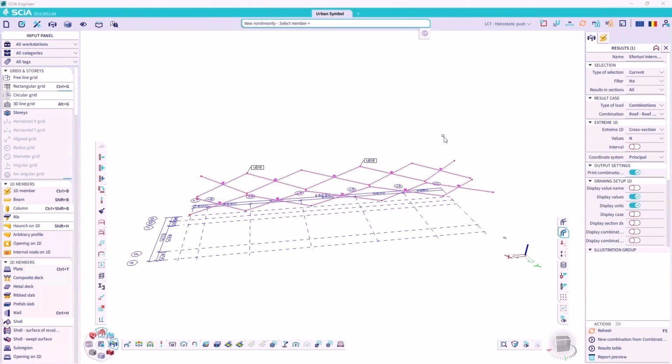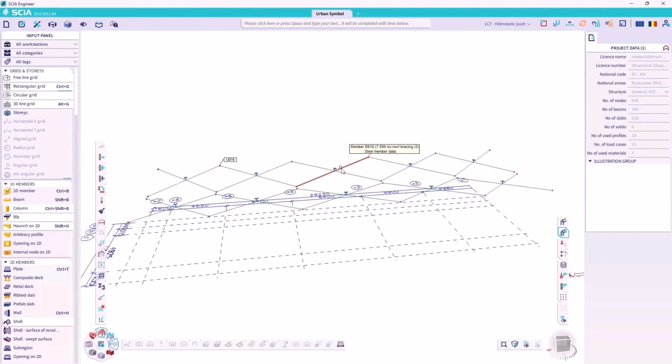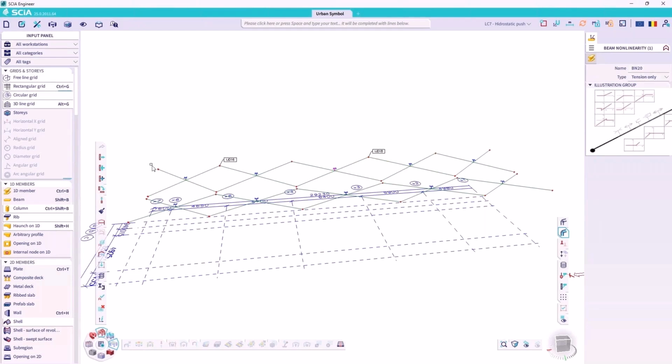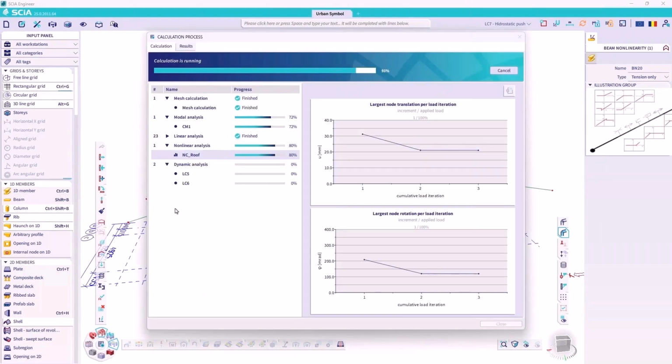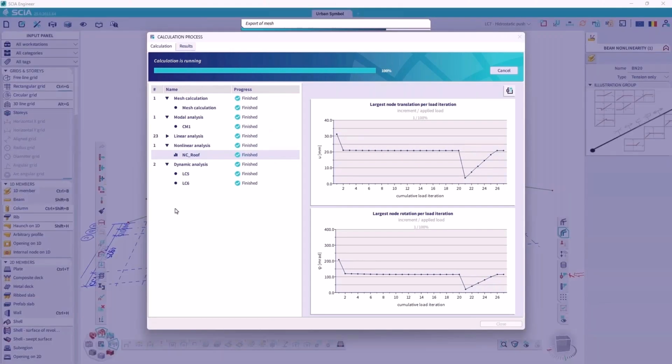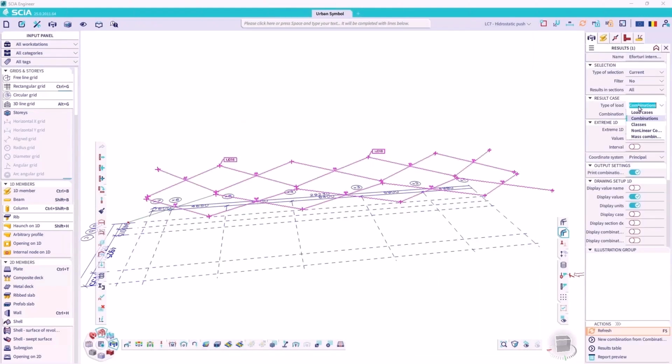And the advantage is not only a reduction in the force or a doubling of the forces and not seeing compression, but we also understand the structural behavior, because if a bracing gets loaded with twice the force, let's say, because the compressed one will buckle, we'll get an understanding of what happens to the joint and the entire structure downwards towards the foundation. So we see here a quick nonlinear analysis, which redistributes the forces so that we only have tension in the members.